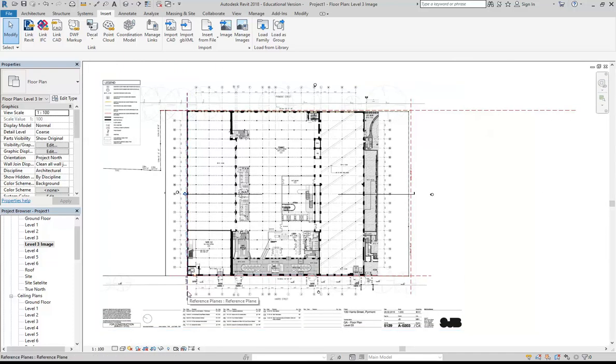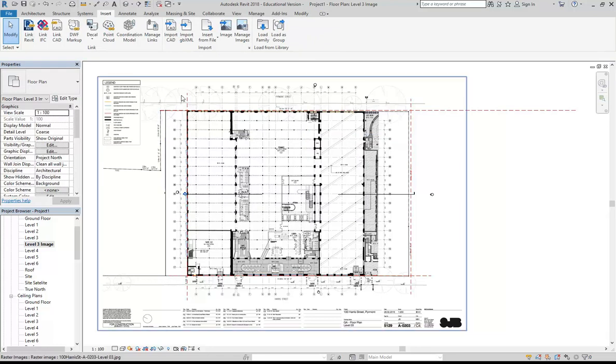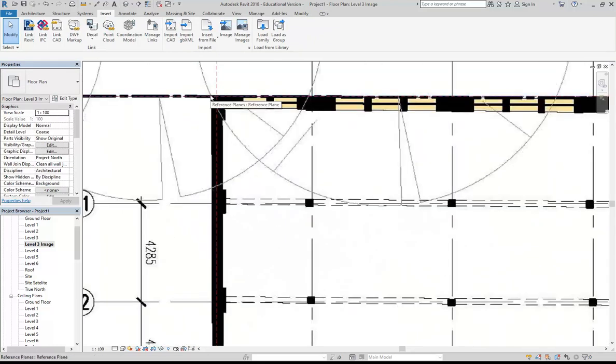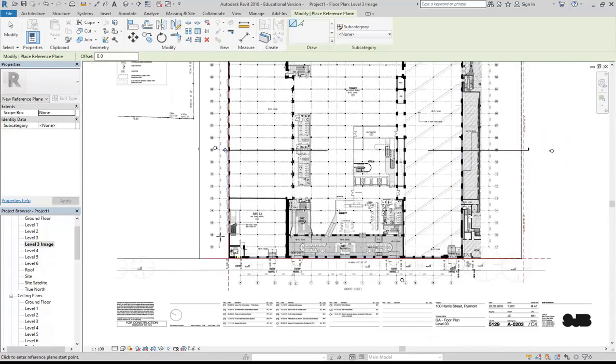With Revit, you want to have the reference planes there, like I've done them, and keep them horizontal and vertical, so that you can see them in the elevation views. But then you'll need some more following the angles. So I'll use reference planes first to do those angles, and then we'll look at the property line.